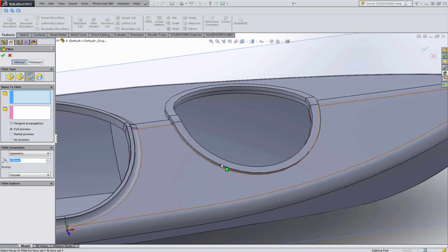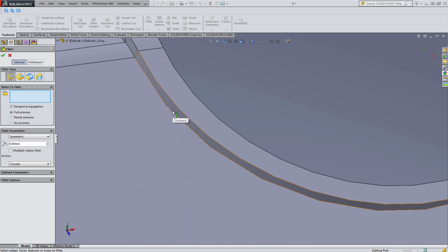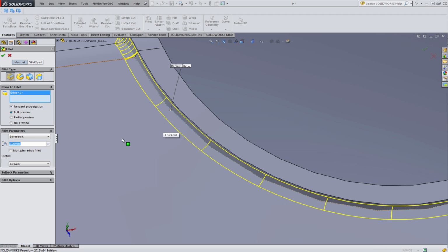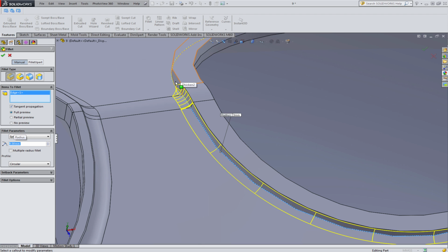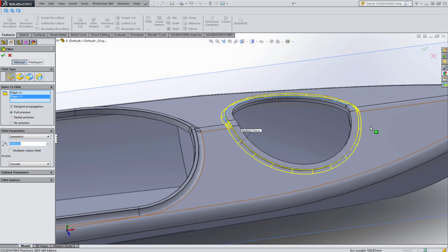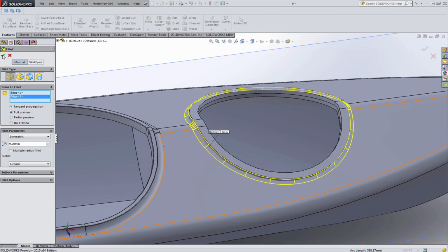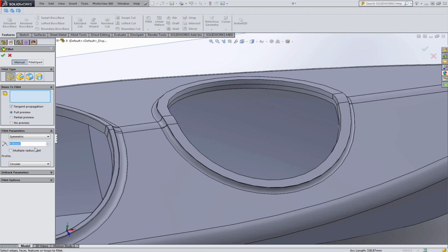The last thing I will do on this tutorial is adding cosmetic fillets, just to make this slot look more attractive. It is general recommendation to save the cosmetic fillets for the last. Try to add cosmetic fillets after most other geometry is in place, because if you add them earlier, like I did, it will take longer to rebuild the part.